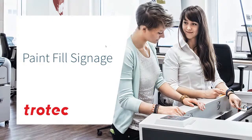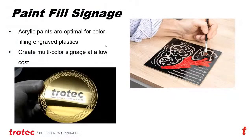Now, taking it a step further from just engraving is paint filling. Paint filling is popular in the signage industry because it allows you to work with materials that don't necessarily give you the correct color, and then add the color necessary to fulfill a customer logo, for example. And so paint filling is a great solution. Lasers are going to give you the ability to do the paint fill by working with different plastics and different paints. Acrylic paints are ideal because they are UV stable, and they also work well with plastics.